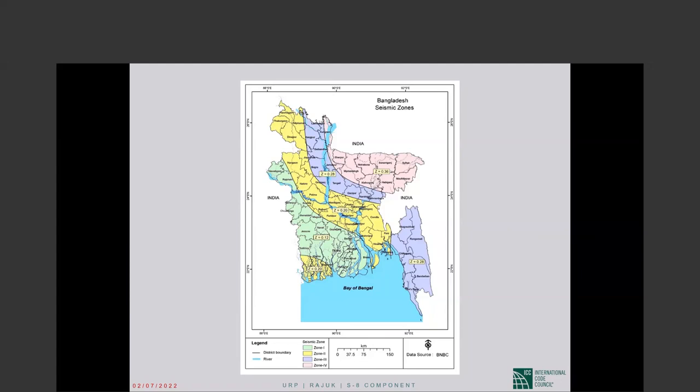Any detailing from collector to shear wall? So, the detailing requirements for collector to shear wall. I don't know that there is any specific detailing requirement for collectors. We have to have the reinforcement that is needed, and then the overstrength factor on the connection. But there is no special detailing requirement that I'm aware of.